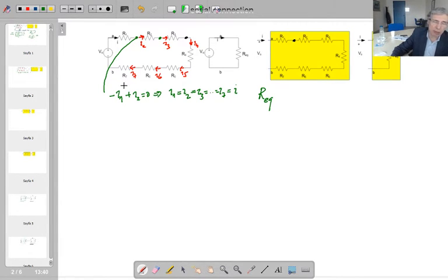So in order to prove that, we've got to write the Kirchhoff voltage law equation as well. This was the Kirchhoff current law equation, and right now the Kirchhoff voltage law equation. In order to write this equation, we've got to choose a loop direction. According to the passive sign convention, the current reference for this independent voltage source is going to be downwards. So if you write the first voltage, the sign is going to be negative because it is the opposite direction of this one and this one. So it's going to be minus Vs plus V1, V2, goes like that until V7. All of their signs are positive because all these current references and the loop direction are in the same direction. Therefore, they are all plus, equal to 0.